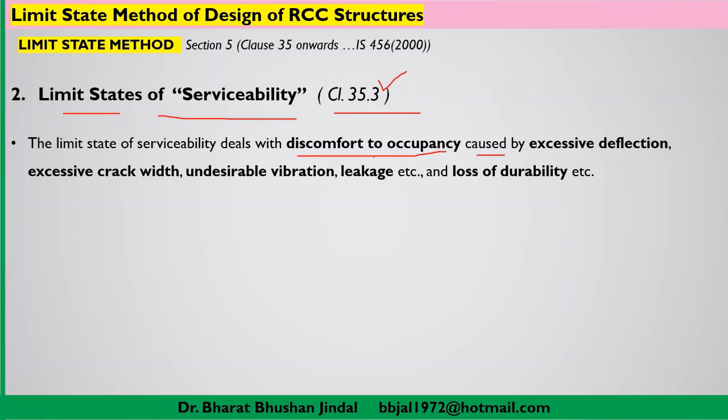That means if the occupants are feeling any discomfort, then we will say the structure has reached the limit state of serviceability. And what type of discomfort? It may be caused by excessive deflection. Suppose there is a beam or a slab, it may get some deflection, but that deflection may be allowed.